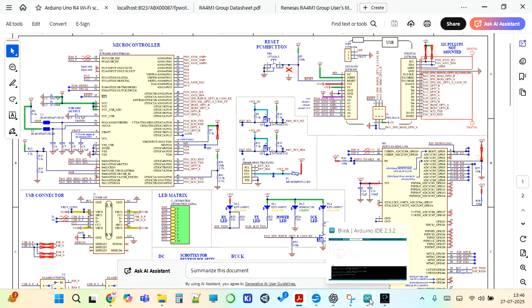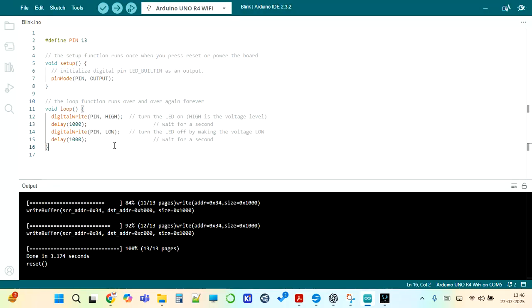Now if you see the code here, the code defines pin 13 as output, and then there is a toggling happening, which we do every 1 second. The inbuilt delay takes milliseconds, so we have created a delay of 1000, that means 1 second. So the pin toggles high and low every 1 second.